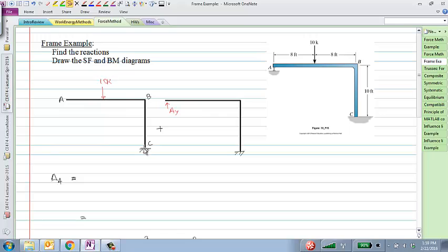It's minus 80 on the vertical member. Minus 80 on the vertical member. That makes sense because this is 10 times this distance 8. So I'll draw that on the negative side. And I'll draw that in blue because this is the actual load. So minus 80. And minus 80 is 0.